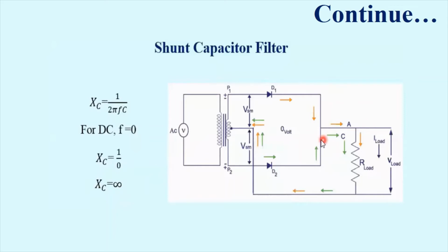So now if we connect capacitor in series with the load resistance, we have at the output of our load no DC, because right there we have AC plus DC, and if we connect capacitor right there, then capacitor, we know, blocks DC signal, so it will block DC signal and no voltage of DC signal will pass through load resistance.